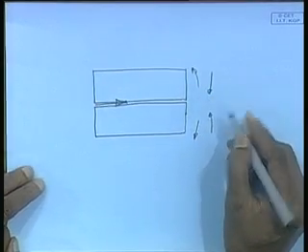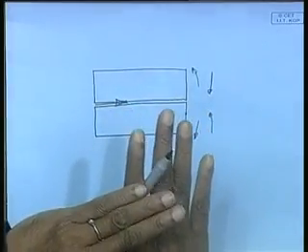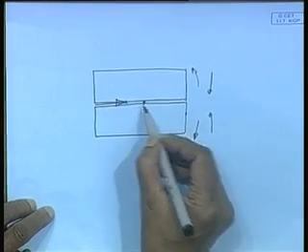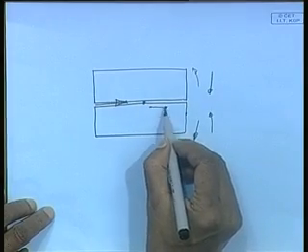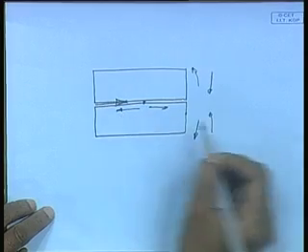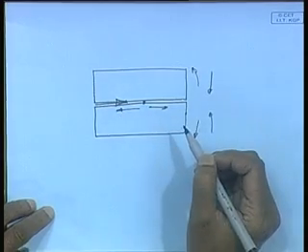If the speed is slow, they may close. If the speed is fast, they may open up, right. So, that was rotational distortion. So, what is the solution given? Solution is start welding from the center simultaneously outwards. This is what is welding sequence.